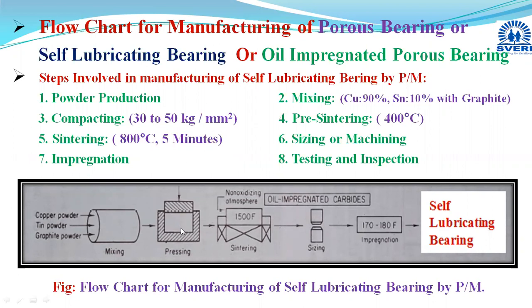this self-lubricating bearing. Then after sufficient pressing, the third step in this compacting process is ejection. Now from this die cavity, by raising this lower punch or plunger, the component is removed from this die cavity, and that removed component, or component obtained at the end of this pressing or compacting stage, is termed as a green compact. Okay, now here during this compacting stage, what changes will occur?